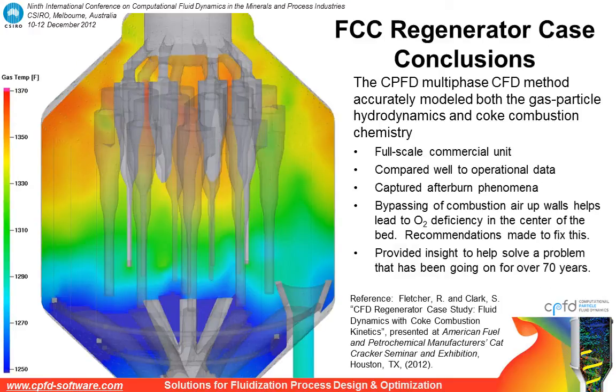In conclusion on this case, it was clear that the CPFD multiphase CFD simulations accurately modeled both the gas particle hydrodynamics and the coke combustion chemistry, at least sufficiently to capture the afterburn phenomenon. This was a full-scale commercial unit, and results of the CFD compared well to operational data.